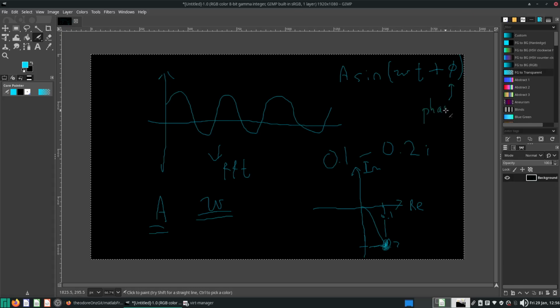And how then do you capture this data? So what Fourier transform does is that it will plot something against the frequency here. It can be angular frequency, or you can even plot it in hertz, whichever is fine. Okay, I prefer plotting in hertz anyway. So you have a frequency spectra.